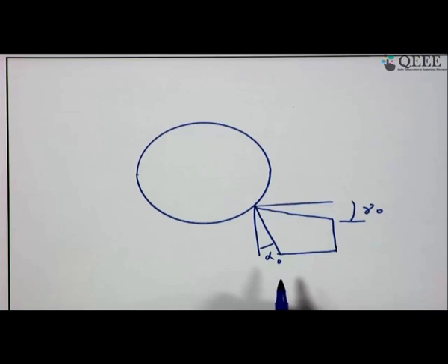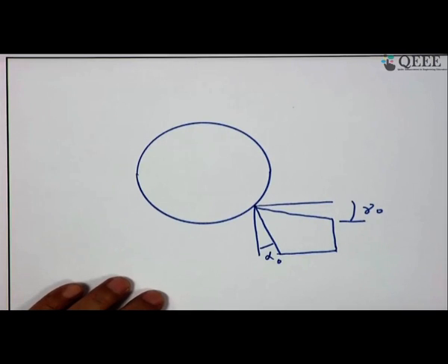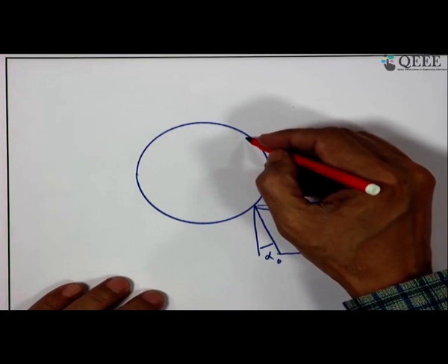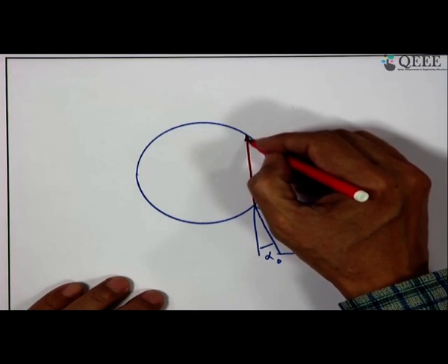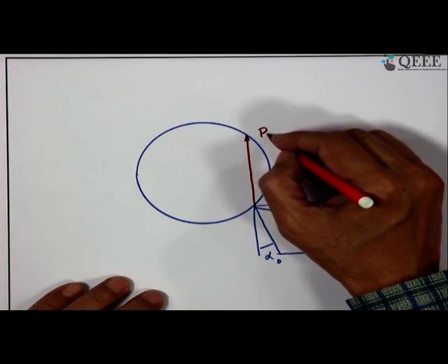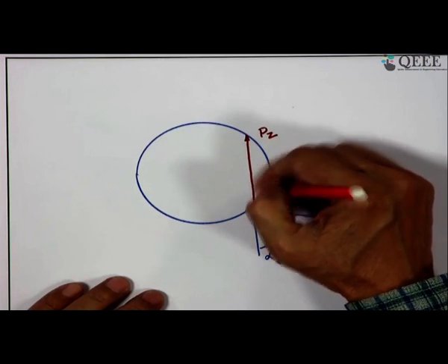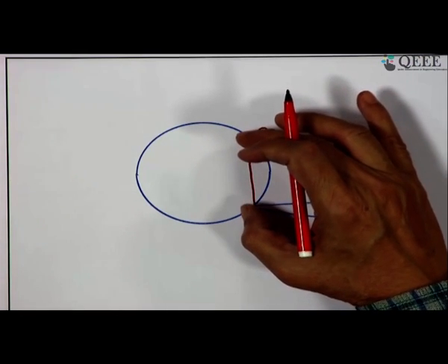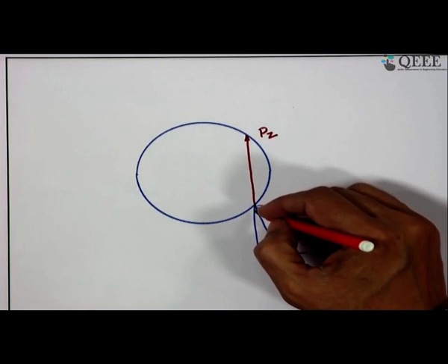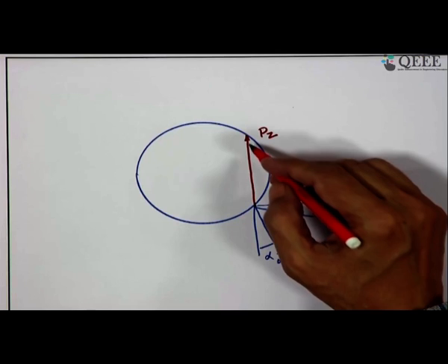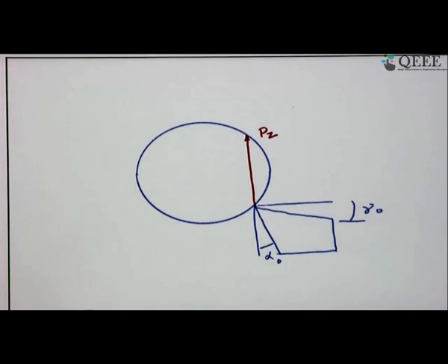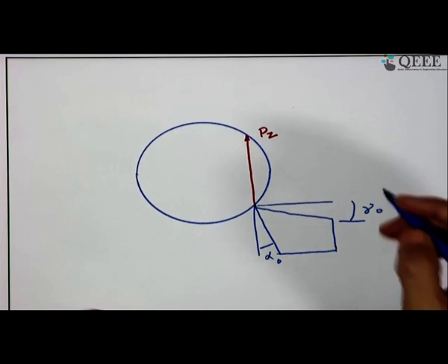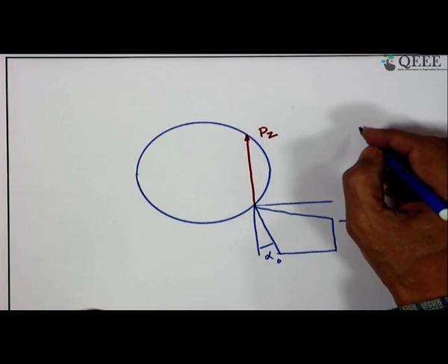We assume that on the tip of the tool all these forces are acting. Now we should show where is the direction of velocity. Definitely this is the direction of velocity. So, I show this is the direction of velocity, and this is in line with Pz. So, Pz will be shown by one chord length and intercept. From this point you draw one line in the direction of velocity, and this chord length shows one force, and that is the Pz force. And at right angle to that we have the Pxy force. How do we get it? Let me explain here too.